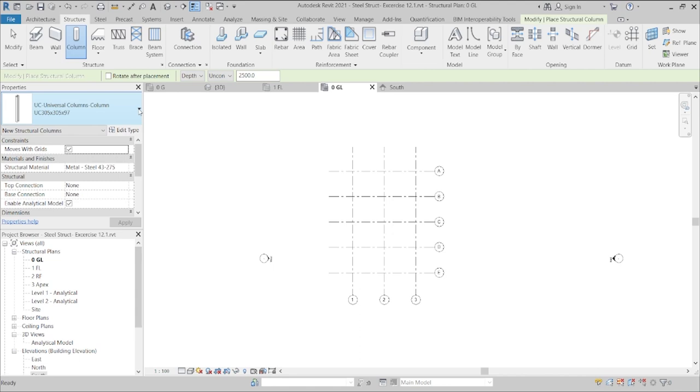But today we don't want the concrete column that you are doing. Today we are going to use the steel columns. So you pick these, the UC, which means universal column. Let us pick the last one, which is 356 by 368 by 129. Pick that, and you can use a grid.